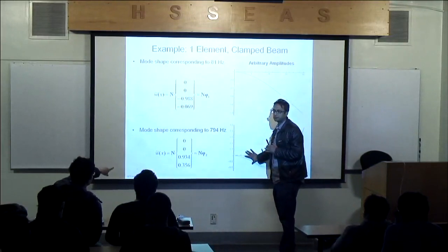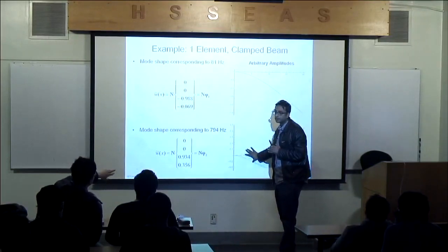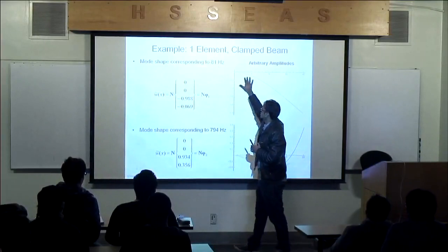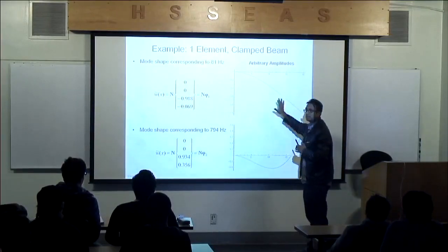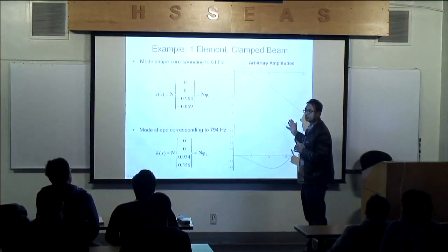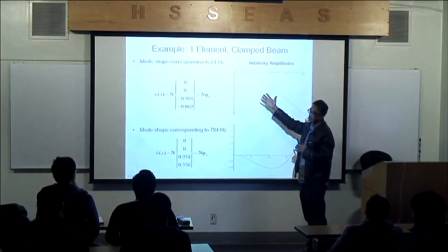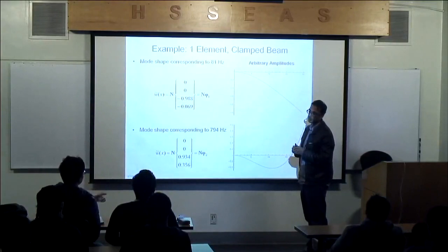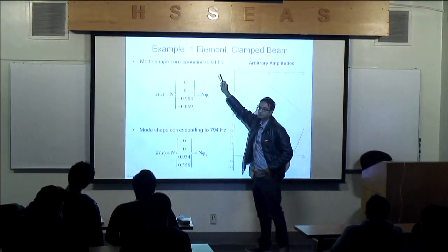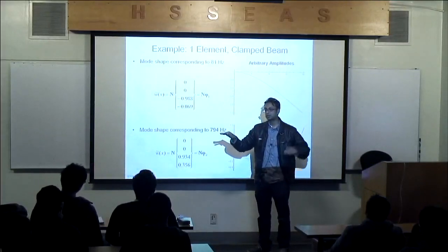Sorry? When given frequencies of 794 and 80. So this frequency is a frequency at which this beam is vibrating. Okay? That's the shape that's taken at that frequency. So it's not frequency from outside. No. This frequency is not the excitation frequency. It's not the force frequency.